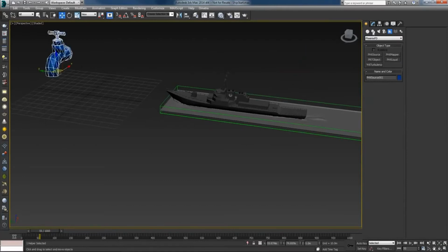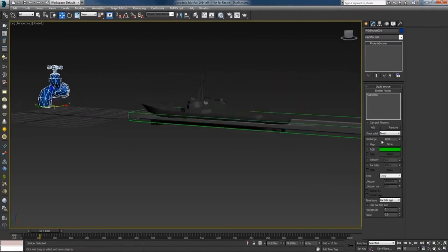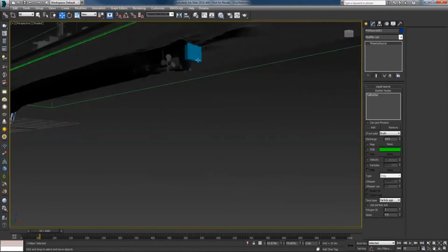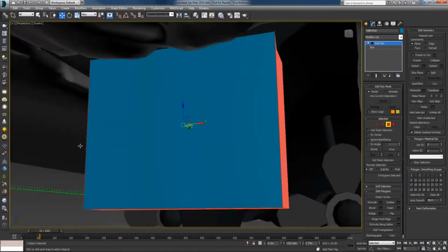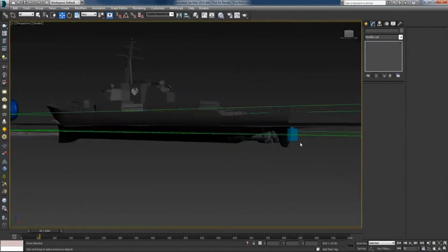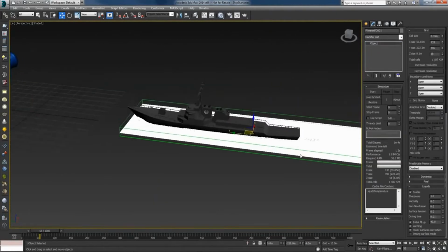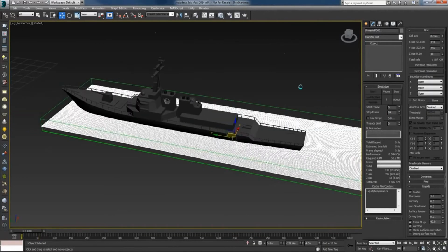And here click the add button and pick the box. I'll set the discharge to 14 and also the polygon ID to 1, so that we only emit from this front face here, and all these other faces are ID 2 and only the front one is ID 1. Okay, so my frame here is 55, so I'll simulate now to frame 54 so that we can compare the two frames, and hit start again.